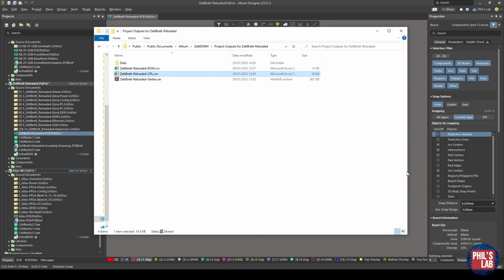However, especially for assembly, it pays off to go that slight bit further and provide assembly drawings. Many manufacturers will also want you to provide these regardless as a necessity. PCBWay doesn't really require assembly drawings, but I always provide them in any case, and I suggest you do the same. This again depends on your ECAD tool, but most ECAD tools will have support for this. Let me show you what a basic assembly drawing looks like and how I would generate one in Altium Designer.